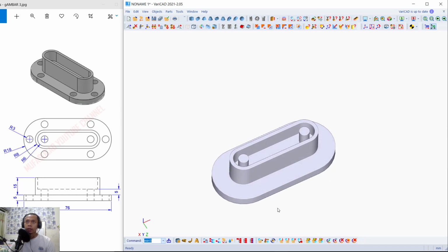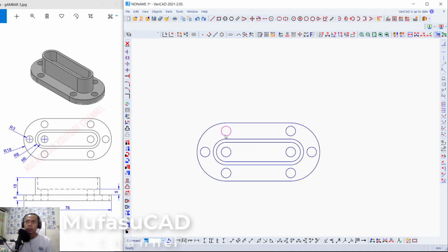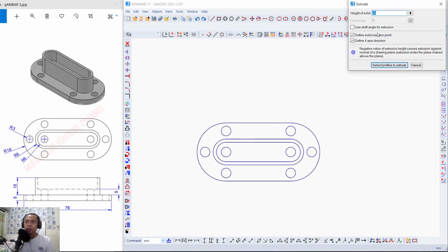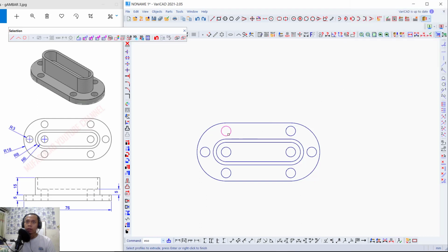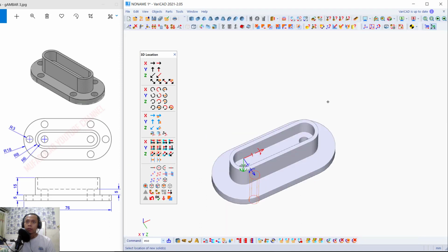The next we can use cut tool again. You can click this command cut, select this object and click in here, click again and click inside. Now we back again into the sketch, and I will extrude these objects. We need to extrude one by one. Okay, select this object for profile, right click, don't forget to set from a center point. Okay, we extrude.